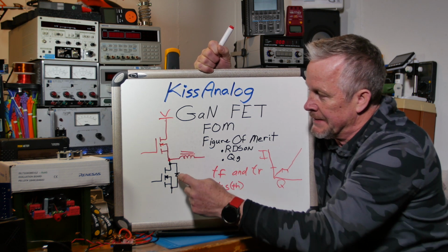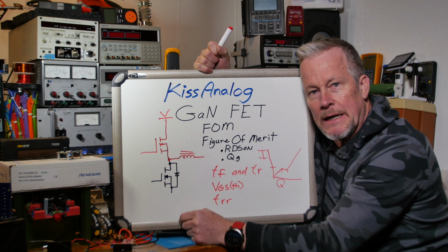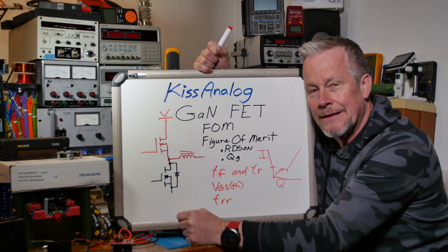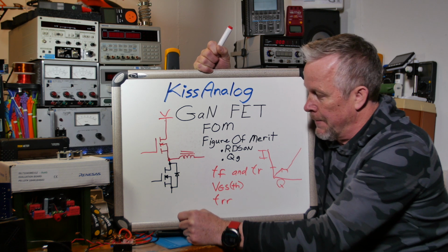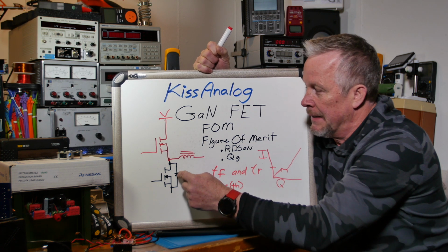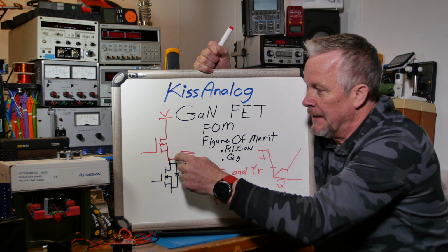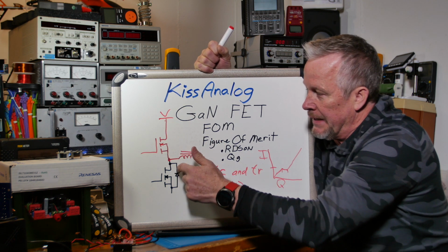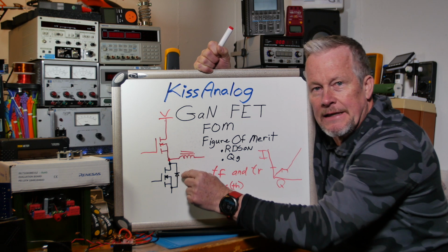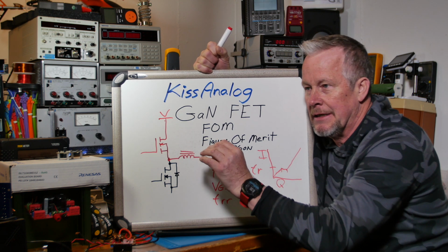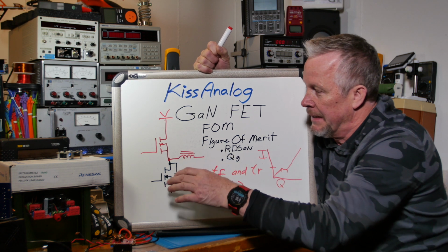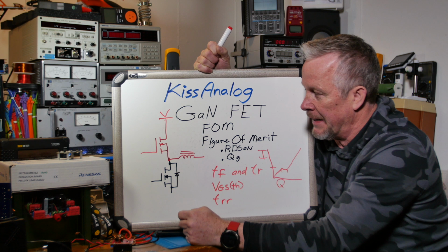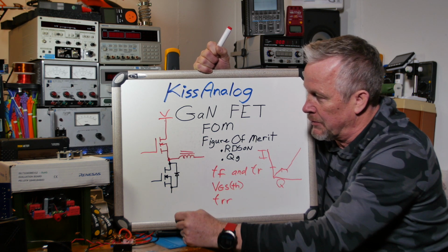When that does, this diode's going to block that current flow from going this way, right? Well, that's true, but not instantaneously. So there's a reverse recovery time. This diode almost looks like it's shorted for a moment when this guy turns on, and then the barrier region inside that diode has a charge and discharge thing that takes place, and then it separates and turns into an open diode again when you have a positive voltage going this way.